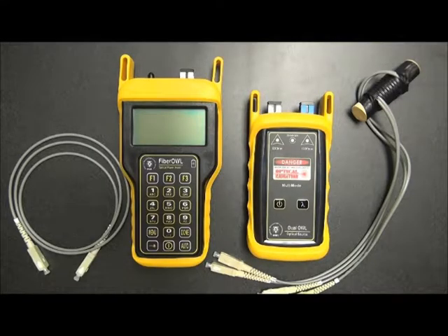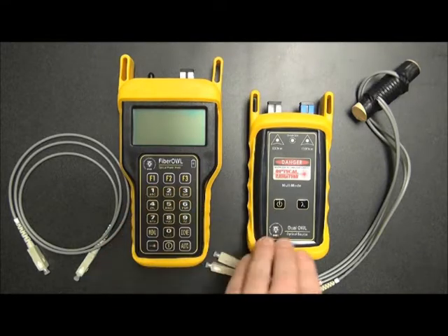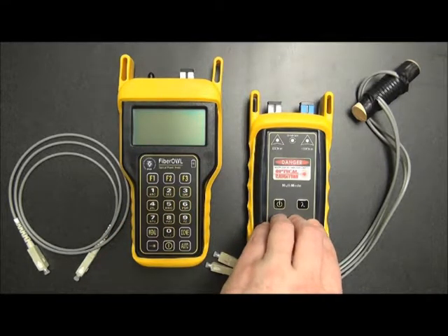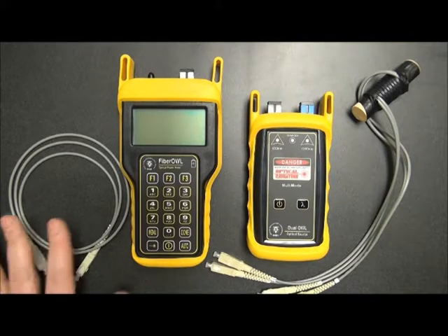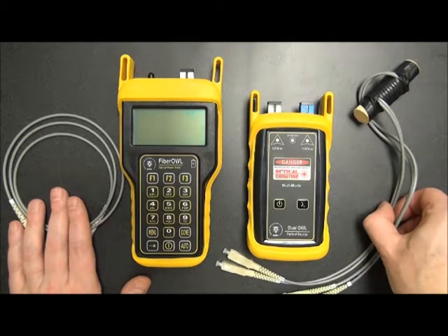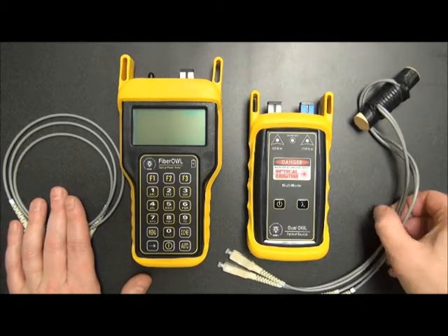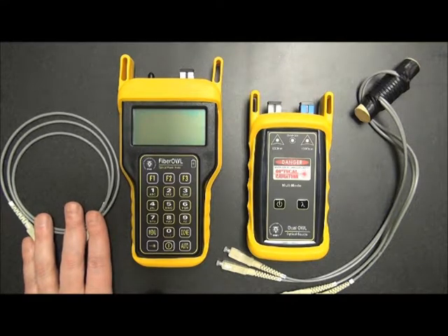Okay, as you can see here, we've gathered our accessories and our equipment that we'll use for this test. In this case, we're using a fiber OWL optical power meter and a dual OWL multimode light source. Now, you can see that we also have 3 patch cables essentially. We have this straight cable and we have 2 mandrel wrapped cables. These will be used for zeroing our equipment. This will be used for connecting the power meter into the link under test when we get to that step.